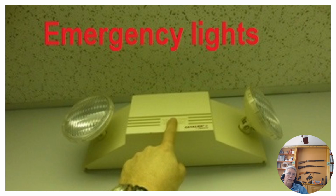Emergency lights is another difference. You'll have emergency lights like this in common areas, hallways and things. They're just like smoke detectors, guys. They're hardwired with battery backups, and you push that button to see if the light comes on or not. And if the light doesn't come on, it's a defect for your report, of course.